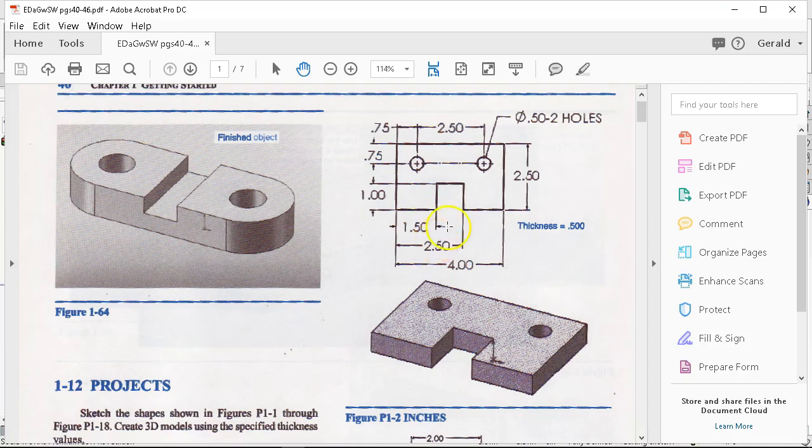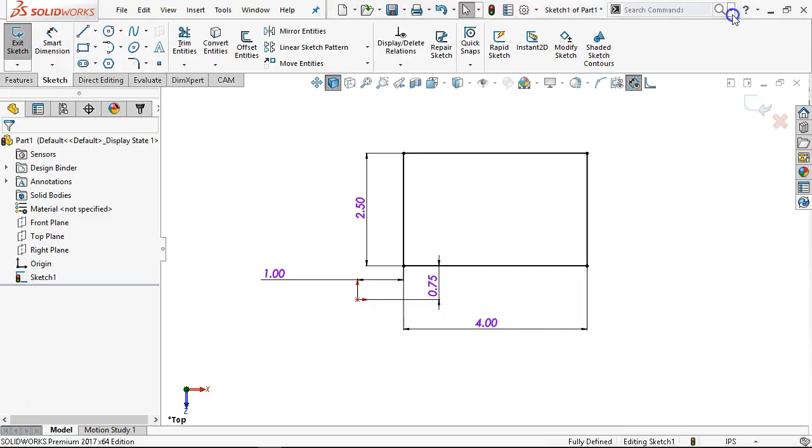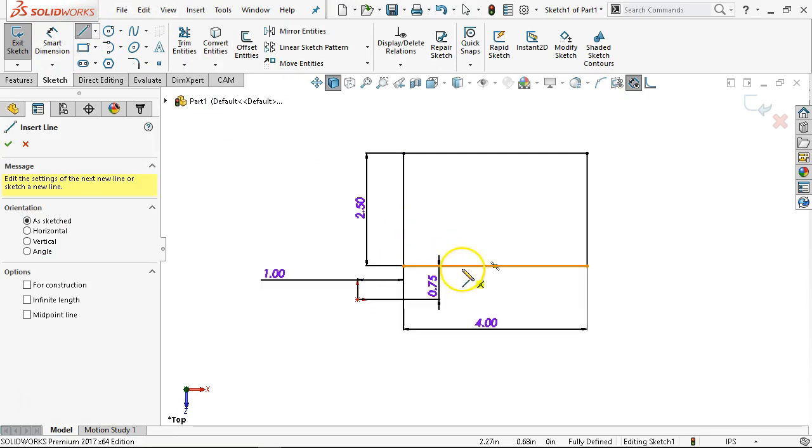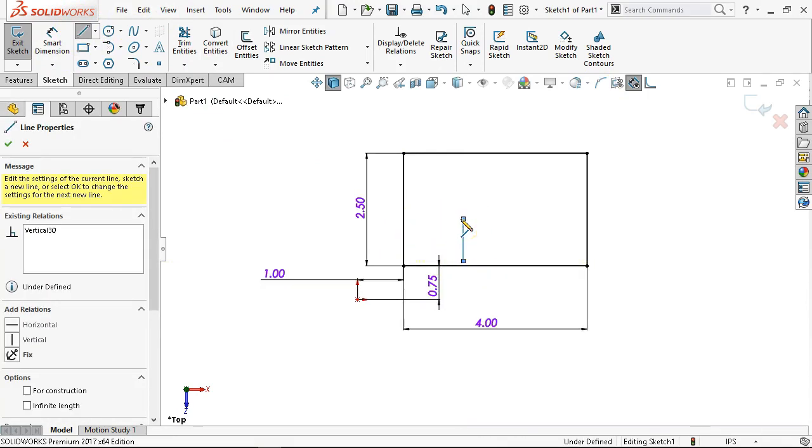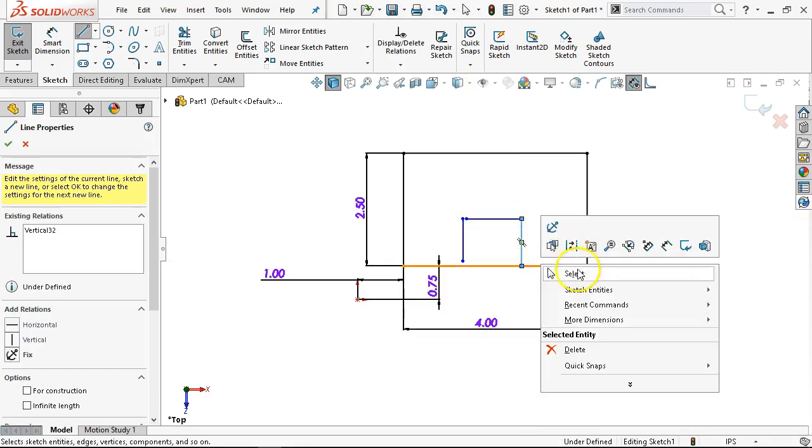We're going to treat this as contours and regions so that we can discuss. I could extrude this out. Now, going into features, this is not a you-have-to-do-it-a-certain-way thing. I could extrude this out. I could draw the 2 circles and extrude it through. I could draw the box and extrude it through. We can draw all the geometry and pick contours and regions. And initially, that's probably what you'll want to do, coming from a 2D CAD background, is generate geometry, but it may not necessarily be what you're expecting or would want to see. So make that one coincident.